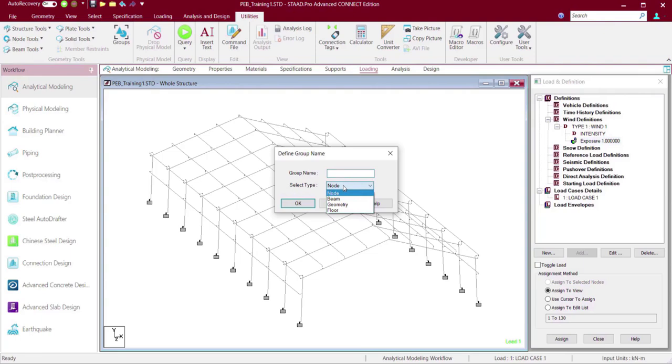Now let's take the dead load because it's a factory shed. Basically, most of the dead load is coming from the self-weight and also from the load which is ascribed to the sheeting and all. Okay, now before we define the floor load, sorry, the dead load, please note that here we have not modeled the roof sheeting, the metal sheeting, with plate elements because there is no point.